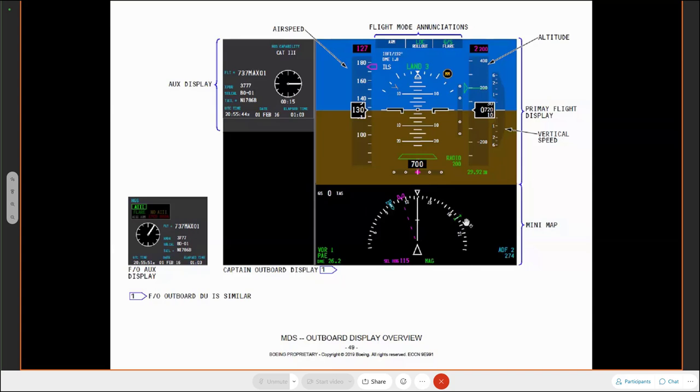You've also got your VOR course pointer here, and then this here is to do with heading. Your selected heading, should I say, that you've got selected on your mode control panel that you would use for your autopilot or your flight director. Okay, on that mode control panel.